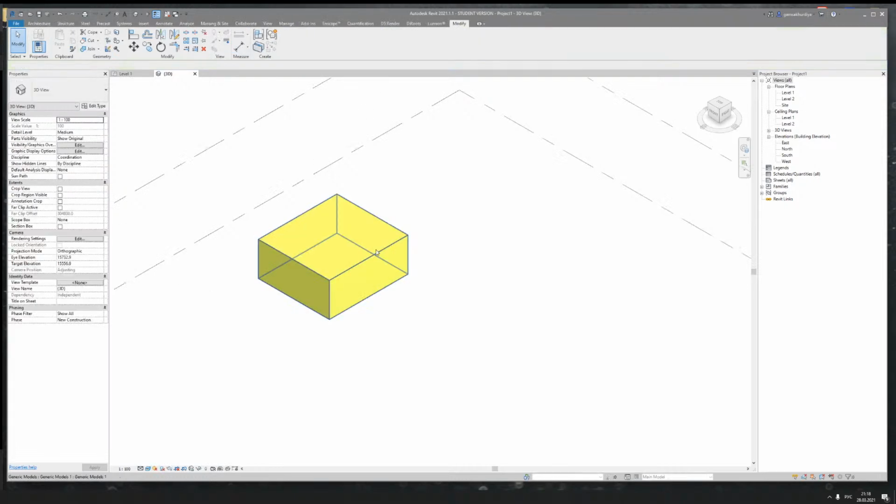Because I don't recommend making models inside Revit, I mean like model in place. If you really don't have any choice, yeah, create a model in place in Revit. It can be done. But if you can create the family, it's better to create the family.